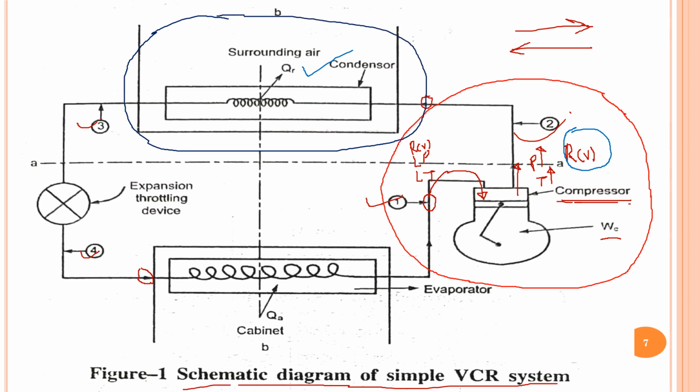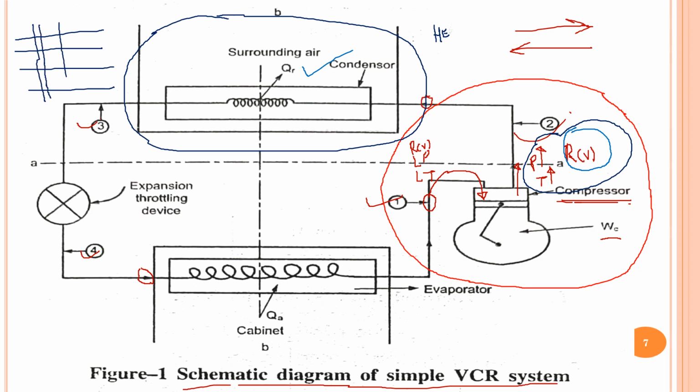Now the second device is a condenser. So high pressure, high temperature refrigerant in vapor form, that will enter into the condenser. This condenser is nothing but a heat exchanger, and in our domestic refrigerator, the heat exchanger or the condenser is located at backside. It is a net-like structure with uneven distribution of fins. You can see this kind of structure is available. It is again painted black. Okay, uneven distance, you can say this is uneven distance. Okay, this is a condenser.